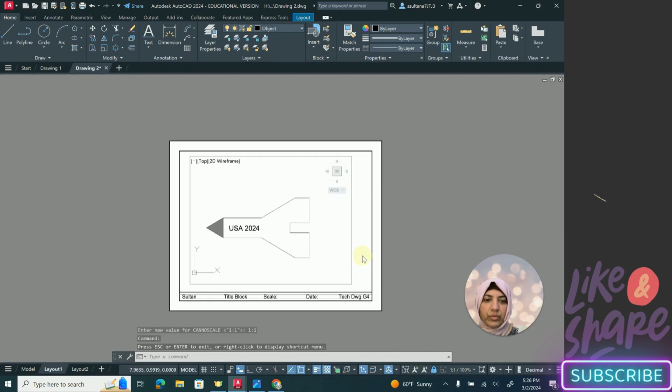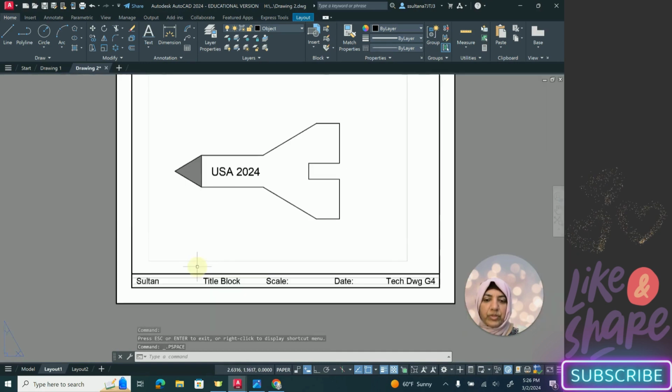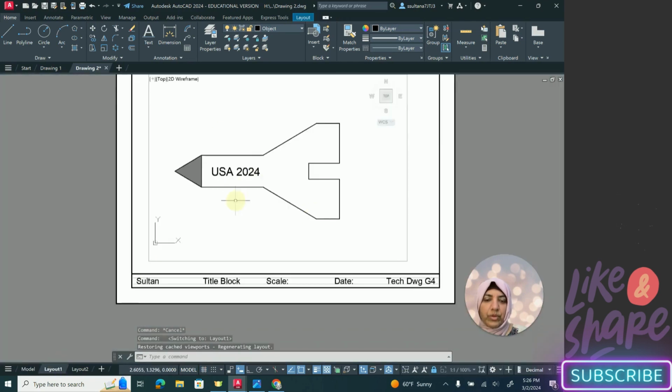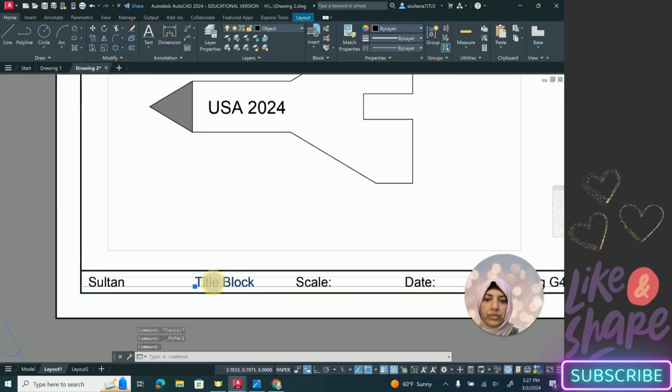Double click outside the viewport, and now you are in paper space. If you double click inside the viewport, you are actually in model space, which is this model space. But through the window, when you double click, you can work on it. See, escape, double click outside the viewport, and then you're going to be in paper space.